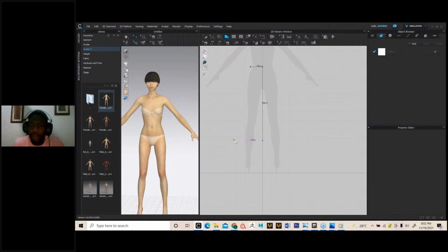So instead of going back and just deleting everything that I deleted, you can actually go back by 1 point, because sometimes you'll have taken a lot of time to actually draw out a pattern, and maybe you just make one simple mistake by clicking on a particular point. So you might want to go back to this point here. If I press Ctrl Z, it's going to take out everything that I've done. So the shortcut to that is that you can simply press backspace. When I press backspace, it takes me 1 point back. You can see.